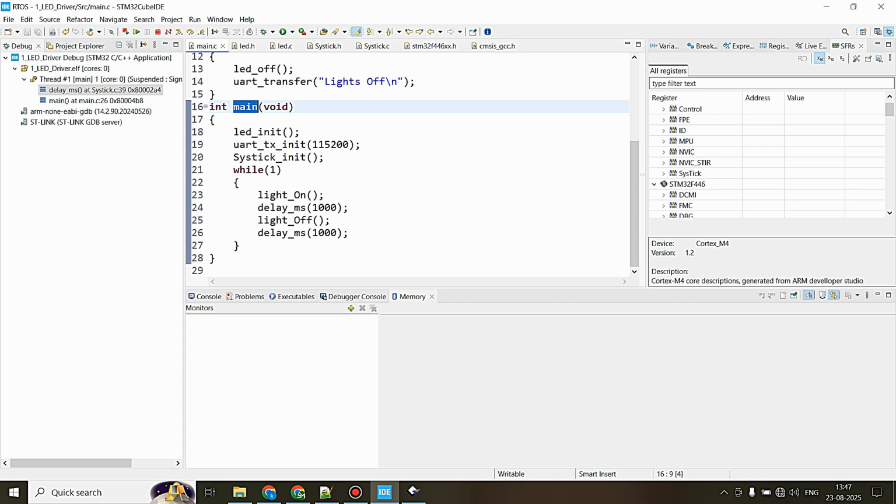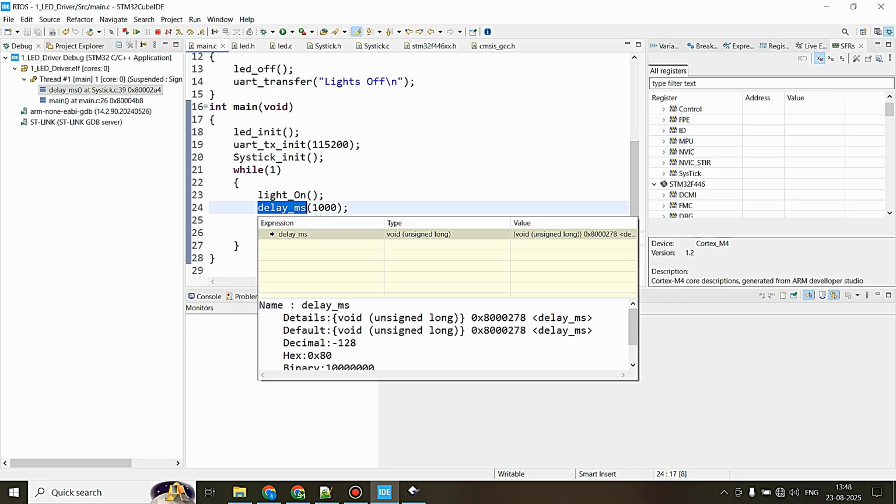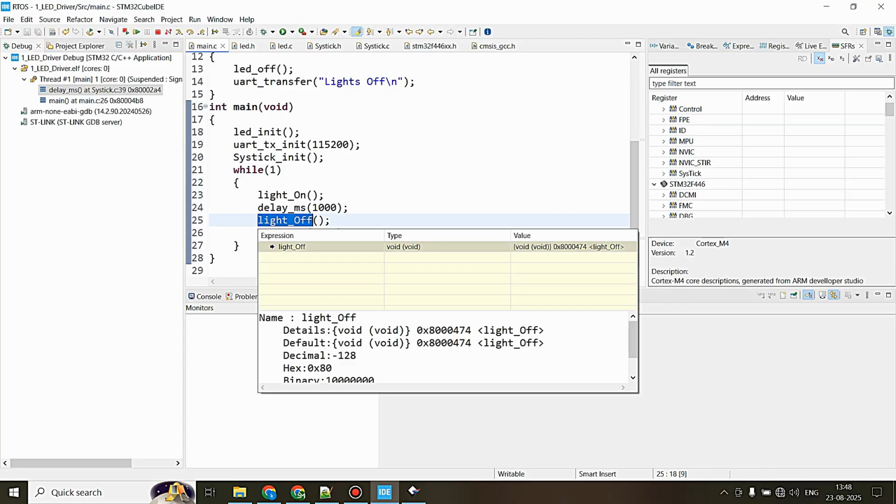And remember, if you are having a serious sensor safety check right over here, and while processing the maximum time in this delay function, we get a particular sensor warning, a safety warning, and the code is blocked right over here. Once the code is released from this particular delay function, it comes to the application software, and this application software actually detects the safety issue after 1 or 2 seconds. That may cause a serious issue in your application or to the operator who is operating your product.